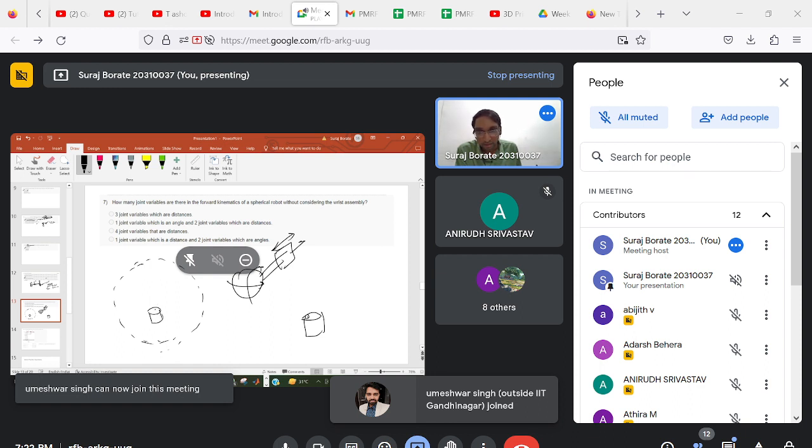So this is one joint, and this is, let's say, an equator of the sphere. You should be able to point at any location on this sphere, and to do that we need only two angles. One you need latitude and one you need longitude. So one revolute joint will ensure that your latitude changes, and then there will be another revolute joint.